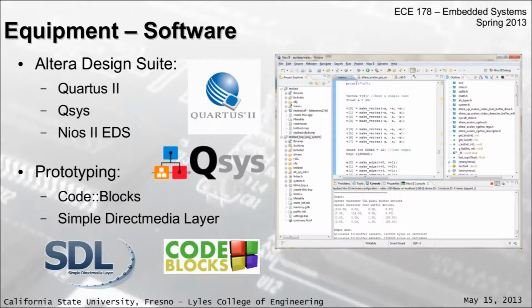For actual programming, we're using the Nios 2 Embedded Development Suite, which you can see pictured on the right-hand side. It's basically Eclipse running plugins for C and C++ and Nios 2. So those of you who have programmed in Java before, it's pretty familiar. It's very similar. So for prototyping, I wrote prototype code to run on the system before I actually had the system running. Prototyping was done in C using SDL, Simple DirectMedia Layer, using the Code::Blocks Integrated Development Environment.